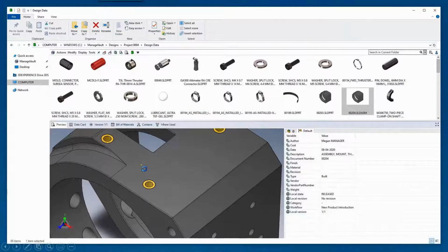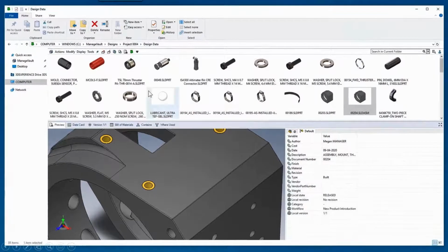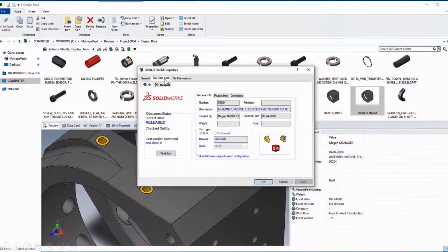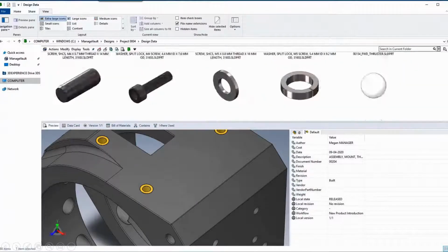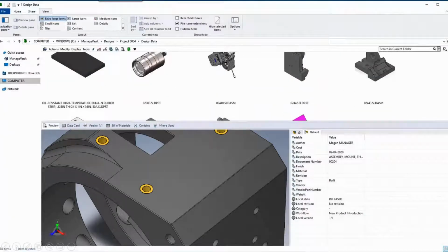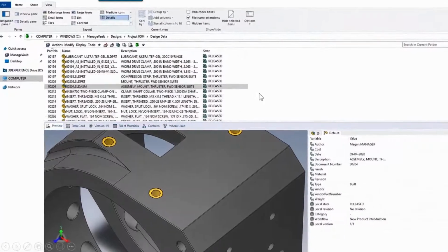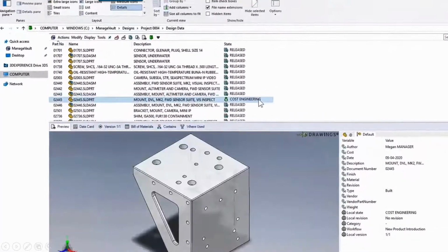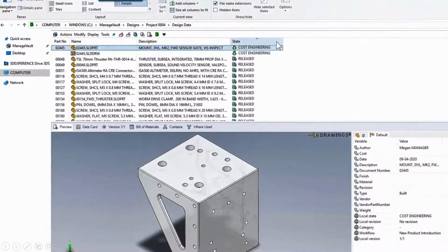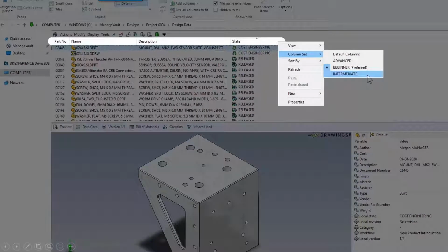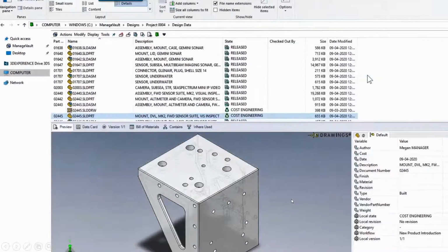One of the best features of SOLIDWORKS PDM is its integration with Windows Explorer. In 2021, the Windows 10 ribbon interface is extended into the Vault view itself. While thumbnails are visually appealing, Details view is where the power of PDM is revealed. Columns expose specific sets of visible properties to users as they work in Details view. In PDM 2021, you can customize these even further in more places and provide choices with multiple column sets.